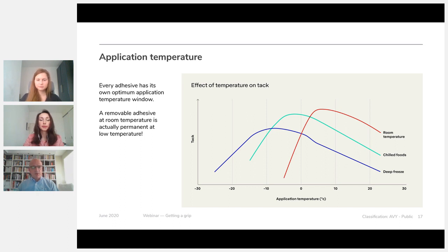With these three points, you have a very good handle on the choice of the adhesive that you have to consider. If you then add the additional requirements, such as UV stability, food approval, or perhaps removability into the picture, then you have a pretty good handle on what adhesive you have to recommend for the end use.